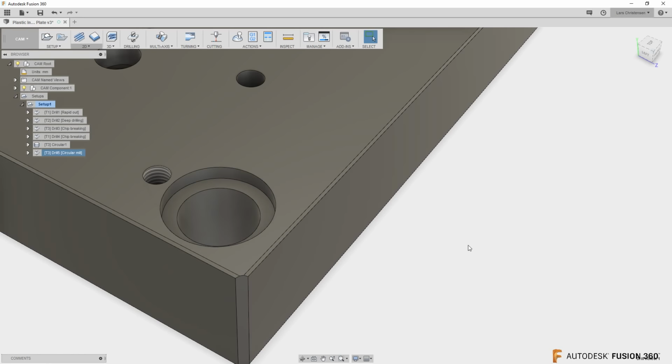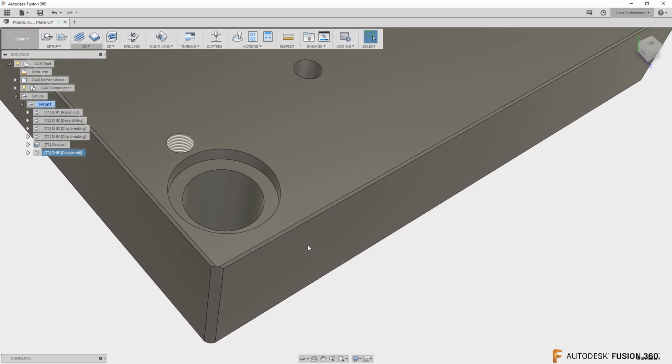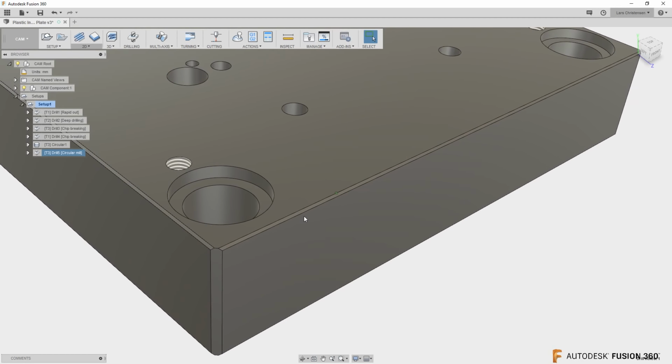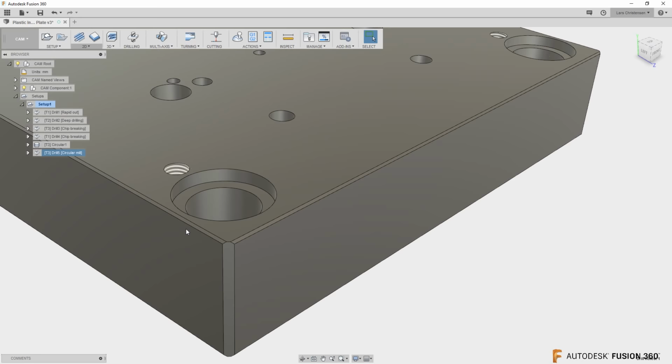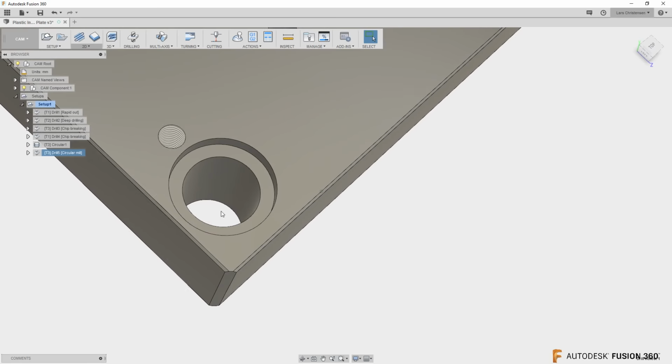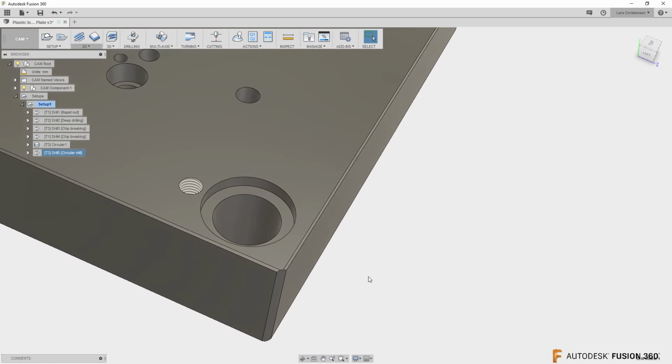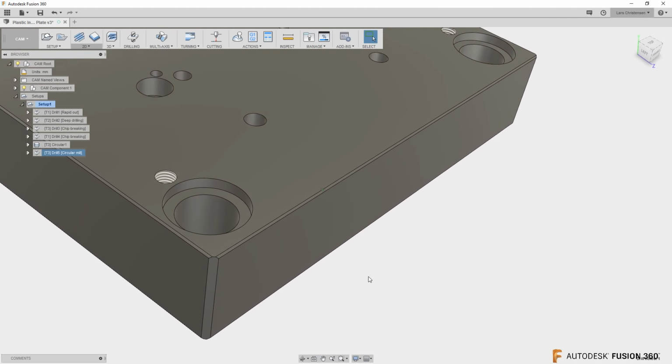Now the last thing I wanted to talk about in regards to straight holes is that, especially if you're machining things that are hard, one of the issues can be tool deflection on a long hole like this. This is a long hole down to the bottom, and you might want to use a bore, but I've also many times done this with an end mill. I've machined that out. But one of the problems you can run into when you are machining something like this is that your tool will deflect.